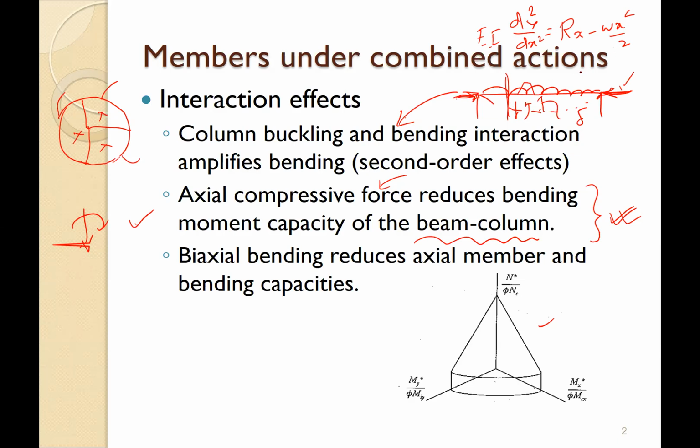If you look at the sine component here, this will produce the same directional moment, which is your axial force. So it will be minus P, if that P is a compressive or axial force, times X. So you see that this P times X is the additional moment which is produced due to this axial load. And this is called the second order effect.